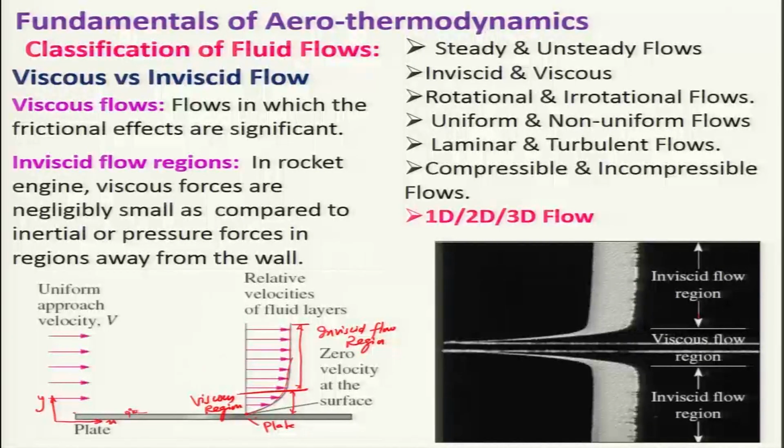If you look at the fluid element, if I consider this as a boundary layer, then the fluid element will be rotating here. Like if you look at this fluid element, it will be rotating, and in this region this will be rotational flow. But in the inviscid region, the fluid element, if it is the element here like this, will remain the same without any rotation. This is basically irrotational flow. In this region, this is basically the irrotational flow region.